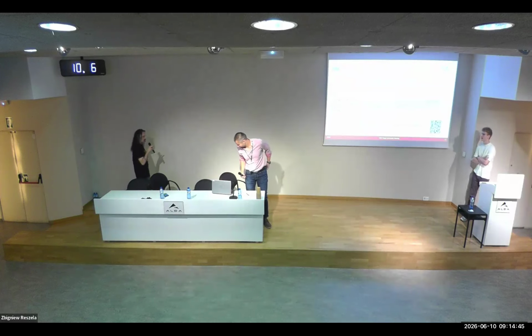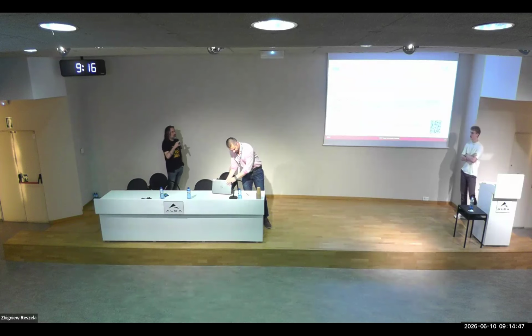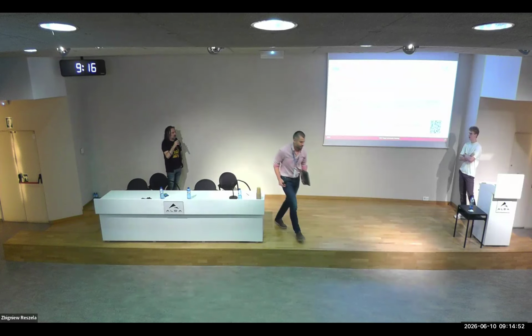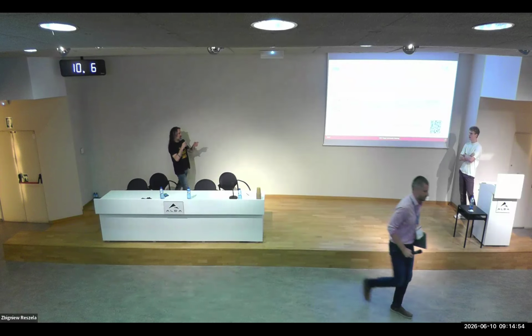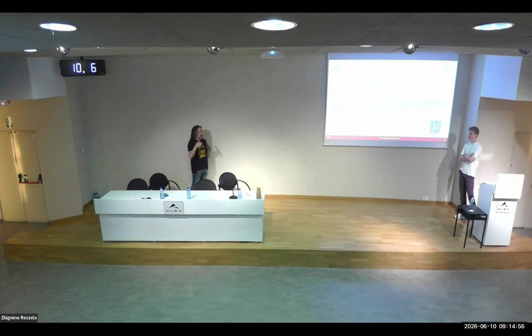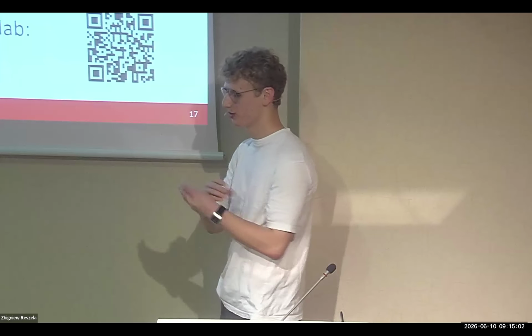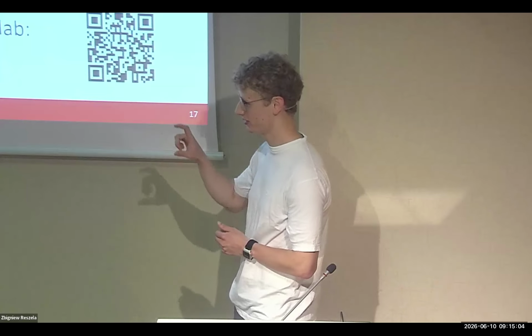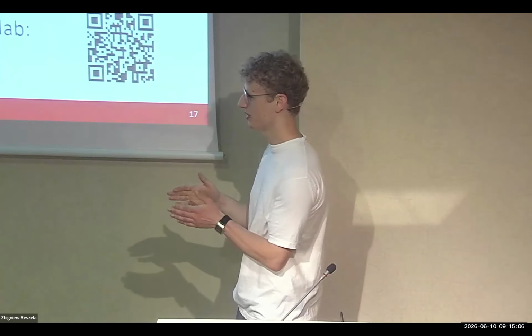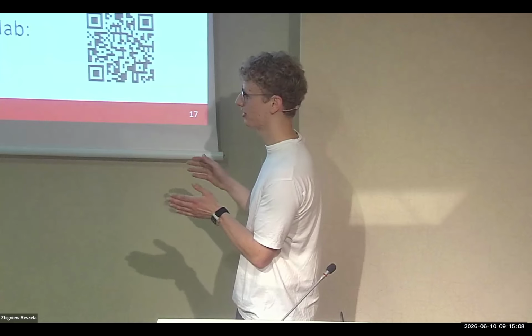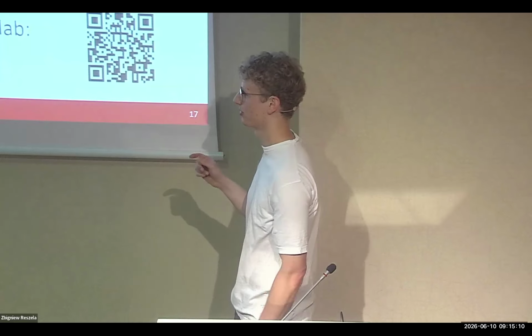In the case of this drift alignment correction, what is the response time of your system? When it detects that the laser has drifted, how long does it take to realign? So when we see it's out of this target region, then before the next shot, always 1 second, we do the correction movement.